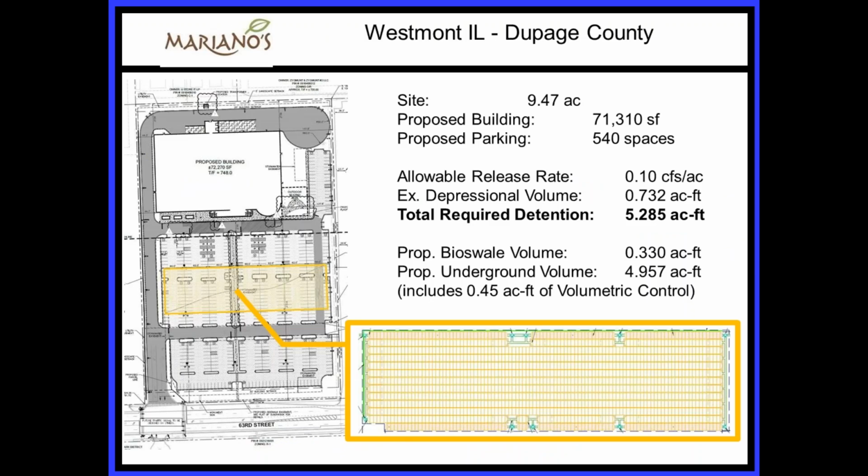A classic example of this is in the DuPage County area in Westmont, Illinois. This was a large Mariano's store, and this is just some of the general design criteria. This particular site had a massive detention requirement in excess of 5 acre-feet. So the design engineer in this case looked at a combination of bioswales or a surface BMP feature, and then said, okay, I have to do something with the rest. So the almost 5 acres was utilizing chambers and storing them under the ground.